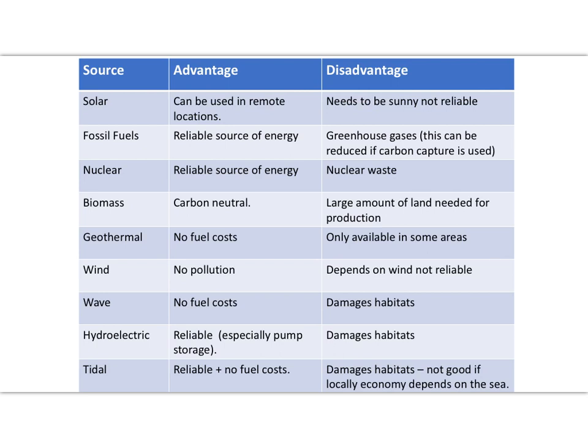Hydroelectric power stations are probably the most reliable of all the renewable sources, especially pumped storage power stations. Remember that in pumped storage power stations, water is pumped back up to the top reservoir during periods of low demand, such as at night time, when electricity is being produced by other renewable energy sources such as wind, and that means that you've always got a constant supply of water in the top reservoir.